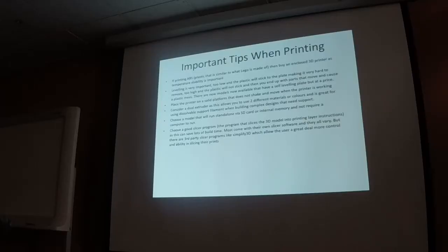Choose a good slicer program, the program that slices our printing into layer instructions, because this can save you a lot of time. The way it decides to print, you want it to be able to print in the most efficient way and save yourself time. And you want to be able to play with some parameters as well. The slicer program will allow you to say, okay, I'm only going to fill in my object at 20%, and I'm going to have my wall thickness 2 layers, 3 or 4 layers. So for the structure you're building, you can say, I want the wall to be 3 layers thick, and it's going to be 20% infill.